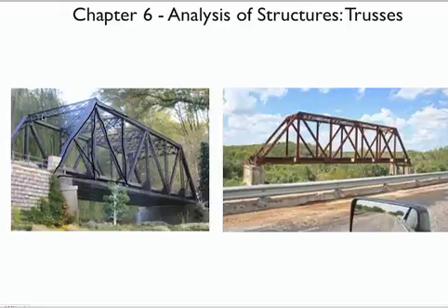And you can also notice too that within these trusses there are these little trusses, right? This beam right here is made up of a whole bunch of straight pieces. There's some structure up in here as well, to keep the 2 sides from collapsing inward. And again, what you get here is a structure that has a lot of resistance to this type of bending as a load is placed on it. Let's say, a train or something like that. So if there's a load sitting on here, this is very stiff and doesn't want to do this, which is good, and that's the advantage of the truss.